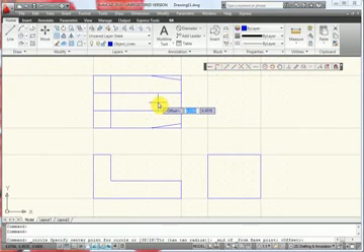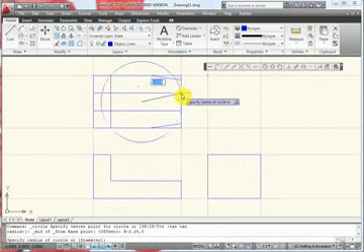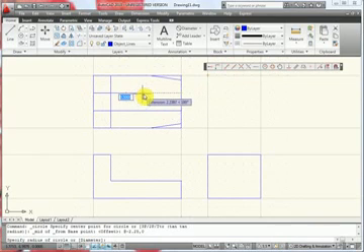And again, these are relative coordinates, so I want to go back. So I type in at -2.25, 0. So it places my circle, and then I don't really have to input a radius because I know what the diameter or the radius is here, which is straight up and down from this point.